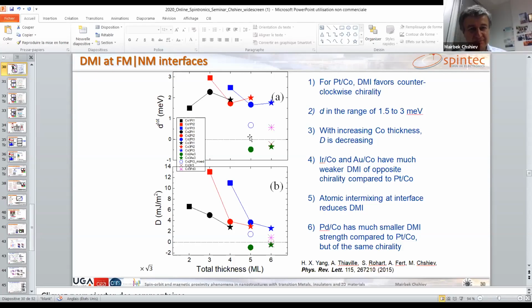I can tell you more on that. In the first observations of PMA at SpinTech in 2002, 2003, 2004, in one of the first experiments, of course with sputtered samples, platinum cobalt was known for PMA and they could see it. Then when they put alumina on top of it first and oxidized it, eventually they put magnesium and then oxidized it, and they saw the anisotropy enhancement.